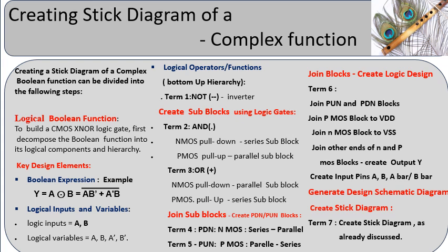Identify and mark input pins. Create text for pins and create the cell boundary. Create the stick diagram as explained earlier.